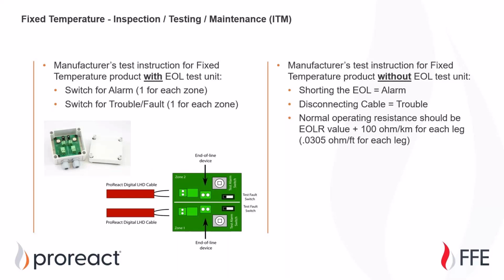Yeah, especially if there was a fire, the outer is gonna melt along with that. If it's more of like a machine overheat type scenario, it might be more subtle. But yeah, there will be clues for sure. If you're going to be relying on your linear heat detection cable to help you determine exactly where a fire event happened, I wouldn't rely on it solely. I'd look for other things to try to investigate that, but usually there are some pretty obvious